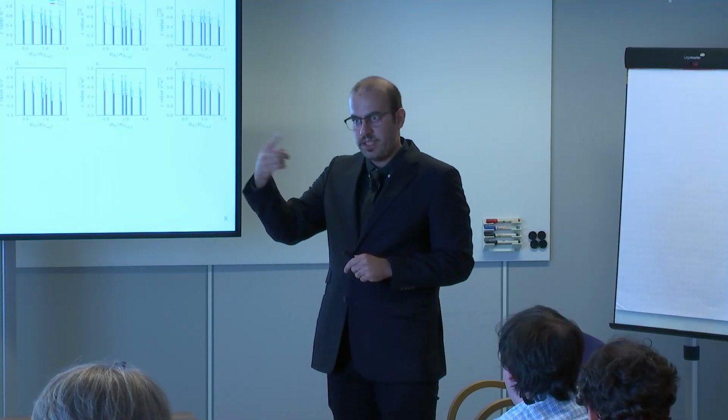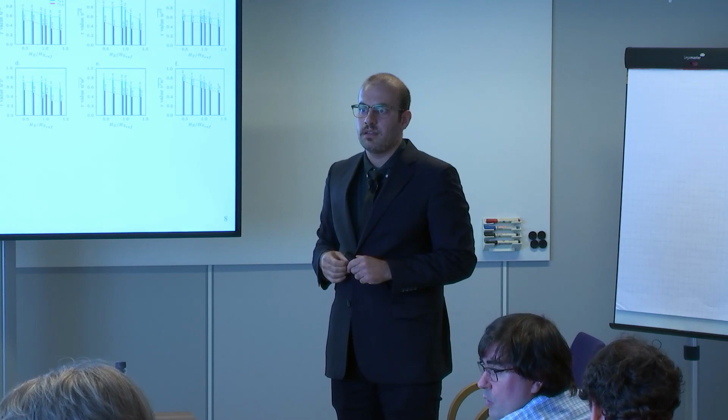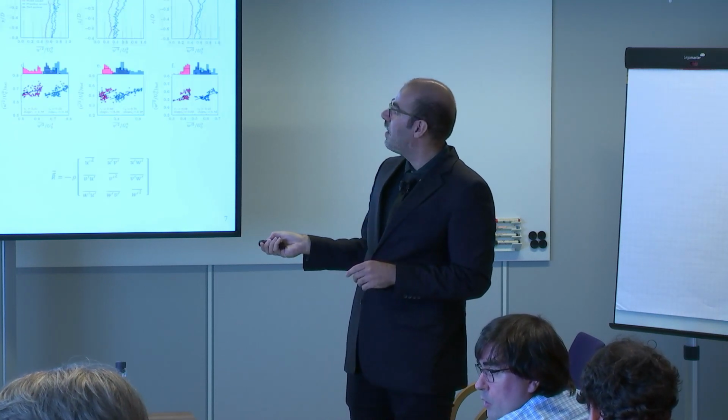Is the rotor also turning, the wind turbine operating? Yes, for the full system, the rotor is also turning. I have the impression that you want to know the viscous damping caused by the hydrodynamics. But if you have a wind turbine running on it, it's known that the aerodynamic damping of a wind turbine is very large. So for the full system, you are mixing aerodynamic damping of the wind turbine, if it's rotating, together with hydrodynamic damping. Yeah, that's correct.